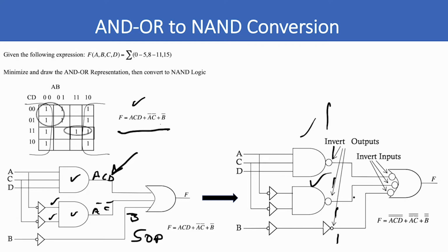Okay. So if you look at this net, we go down to implementing this particular function. This is a 3-input NAND gate, a 3-input NAND gate, a 3-input NAND gate, and then we have 2 inverters. But if we look at this right here, B is inverted to B bar, and then B bar goes back to B again. So we don't need these inverters in the net. So it's just B going directly in.